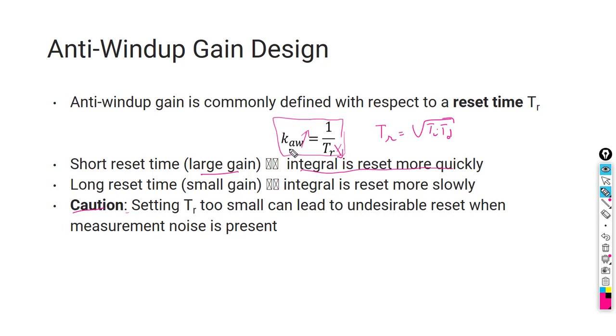But if you have a derivative in your system, then take a compromise between TI and TD. In this way you are quick enough, but at the same time you don't amplify the noise in your measurement. That's the rule we use.